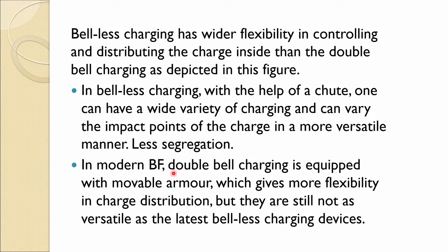So, bell-less charging has wider flexibility in controlling and distributing the charge inside than the double bell charging as depicted in the previous figure. So, in bell-less charging with the help of the chute, one can have a wide variety of charging and can vary the impact point of the charge in a more versatile manner, and you have less segregation. Segregation means smaller and bigger size particles, even based on density difference, the segregation can occur at the point of impact when you are putting the material.